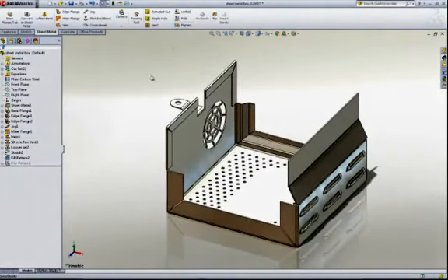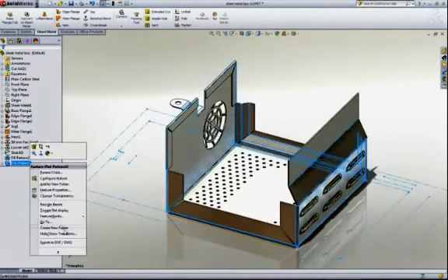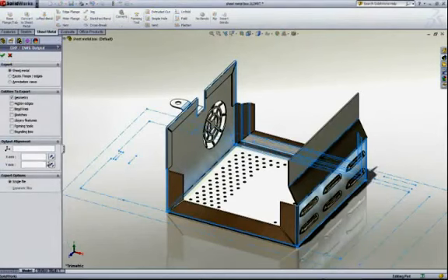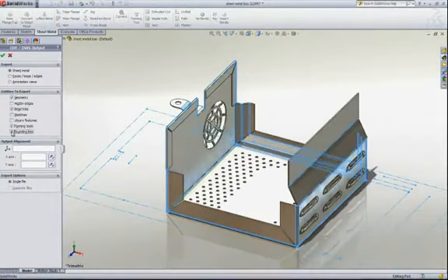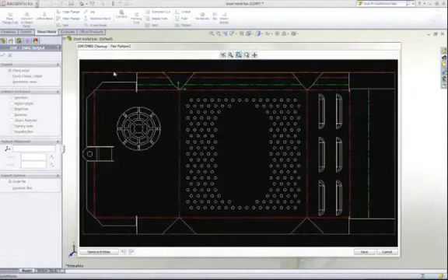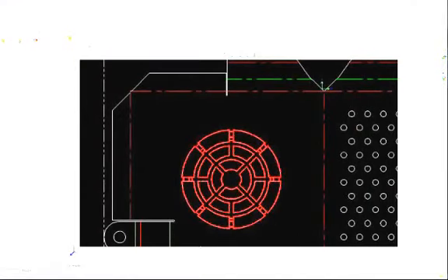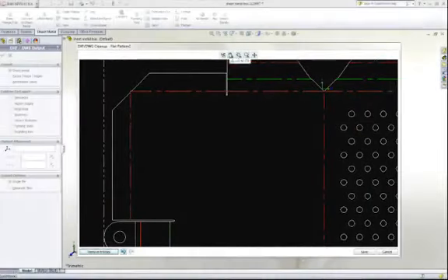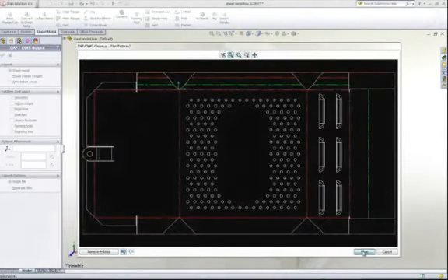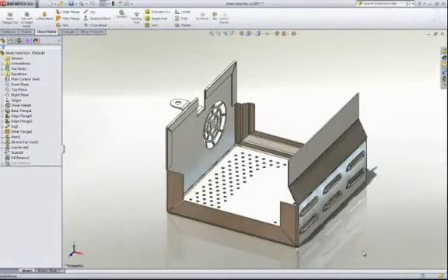It's now a small but significant 1 millimeter shorter. CNC punch presses, laser profilers, waterjet cutters, and offline CAM programs typically take flat pattern profiles in DXF format. SolidWorks lets you directly export the flat pattern, bend lines, form features, and blank size, then present you with a preview window that can be used to clean up your output.